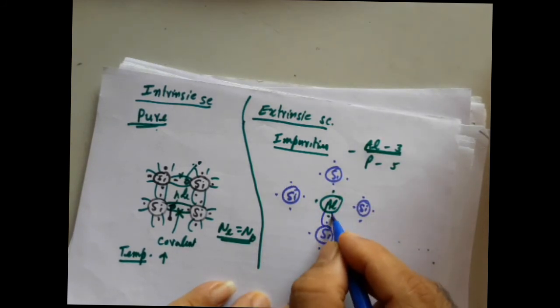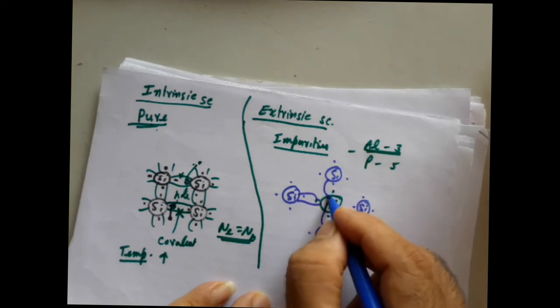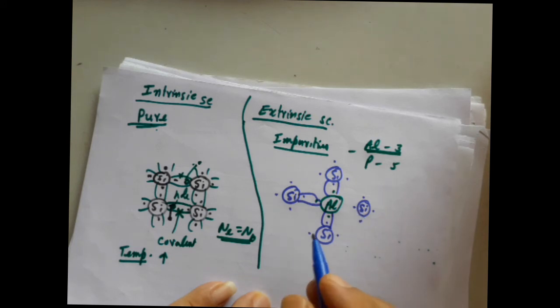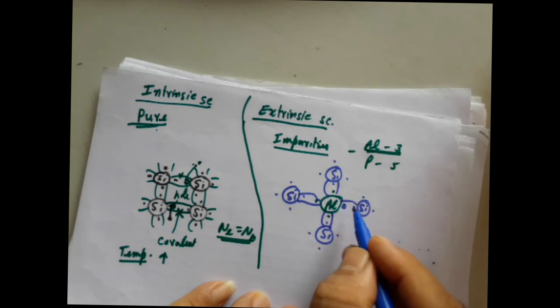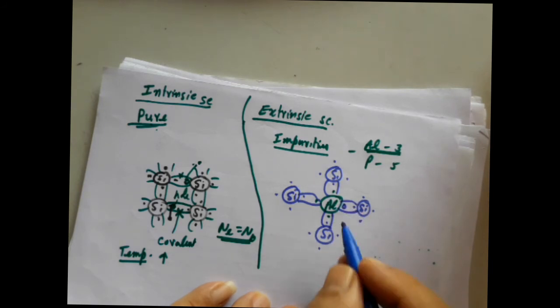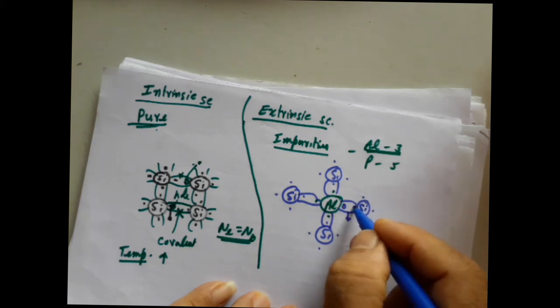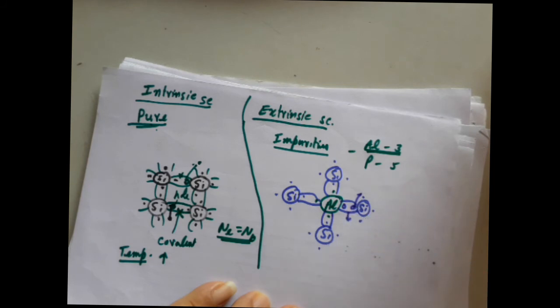and every electron of a silicon atom bonds with its neighbor. But the problem is that aluminum doesn't have an electron to bond with the silicon, hence it creates a hole, a vacancy. Naturally, there is one hole already created in the absence of temperature. Now if I increase the temperature, this bond may break and an electron is freed out, and one more hole is created, and you can see the number of holes is going to be greater than the number of electrons freed out.